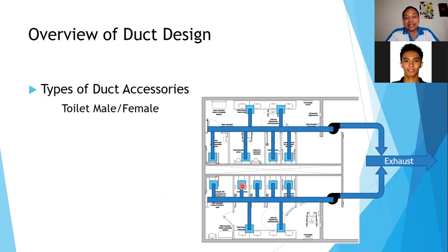Again, this is our proposed ducting layout. And these are the duct accessories needed. So same, you can see there's volume control damper on strategic places. So there should be one more here. But here we put NRD or non-return dampers. So non-return dampers prevent airflow from one side but allow airflow from the other.